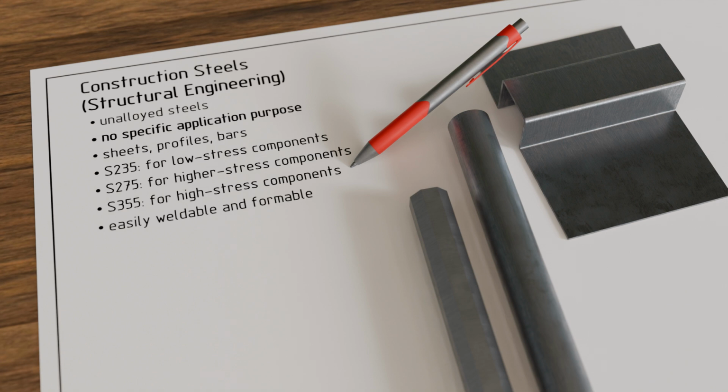However, the manufacturing process of S355 is more complex, making the steel about 10 to 20% more expensive than S235. These structural steels are easily weldable due to their relatively low carbon content. Additionally, they contain few brittle carbon constituents, giving them excellent toughness, which makes them particularly suitable for forming. The carbon content of these structural steels usually does not exceed 0.22%.